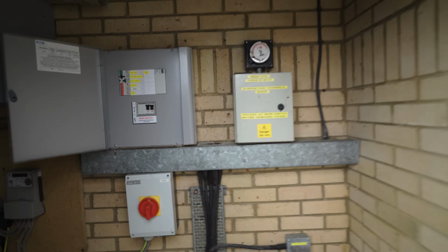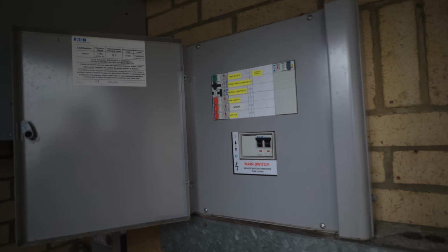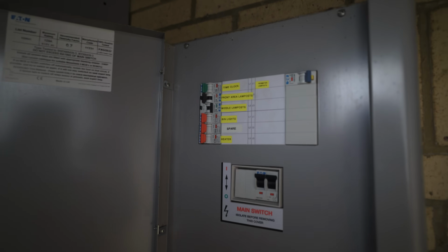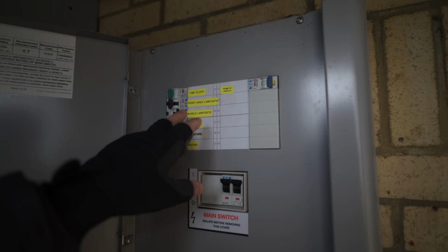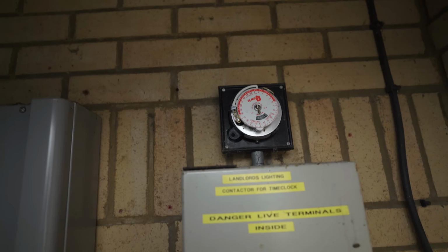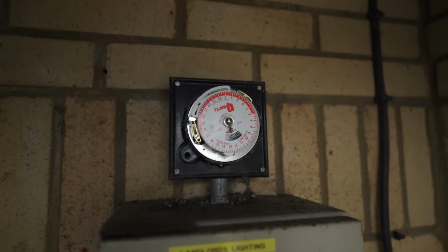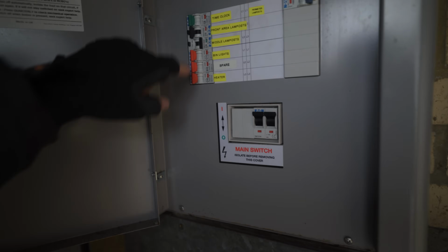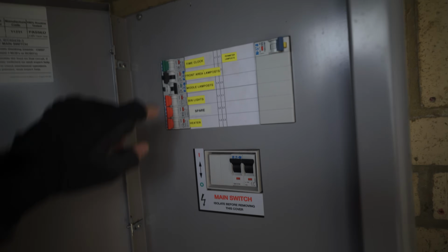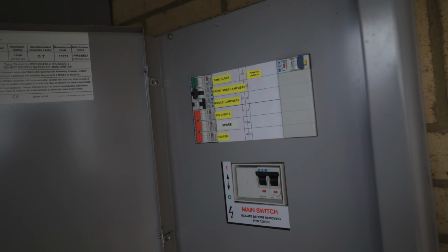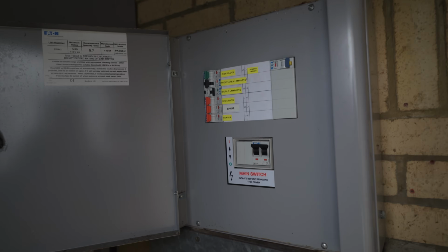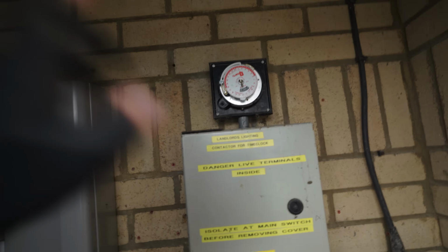This is the switch room, and in here we have our DB. So this is the offending circuit, middle lampposts, there's some other outside lighting circuits and stuff like that. I've got the time clock overridden. It's just an old school time clock, and you can see it doesn't want to stay on. It's on an RCBO, going to make it super sensitive to any of the elements, but there's obviously an issue there with the time clock not overridden.